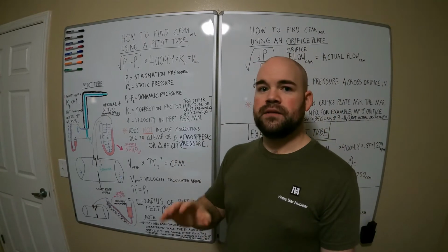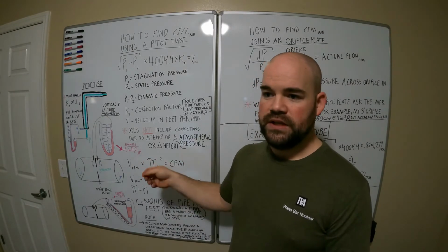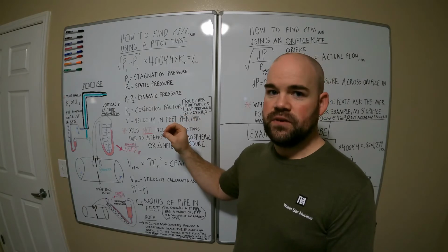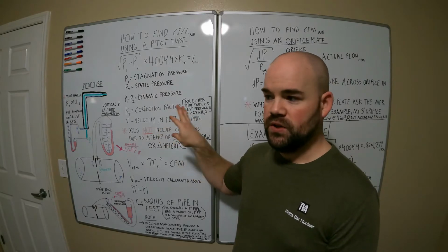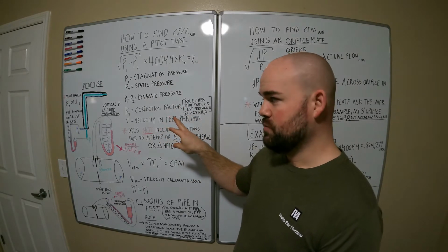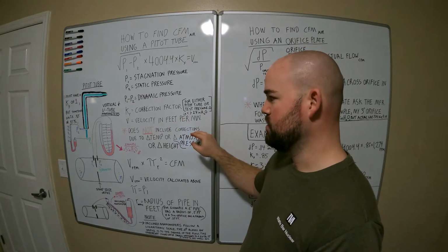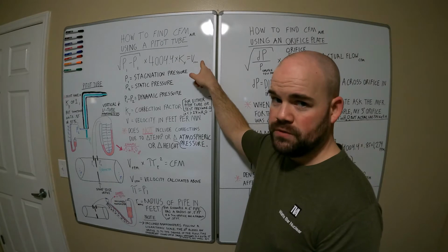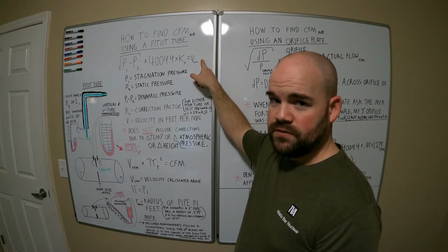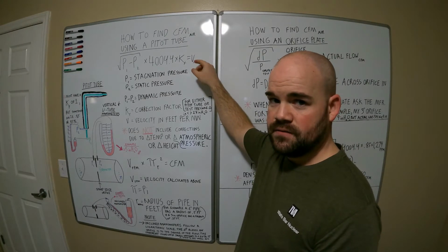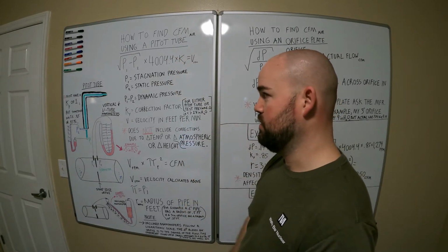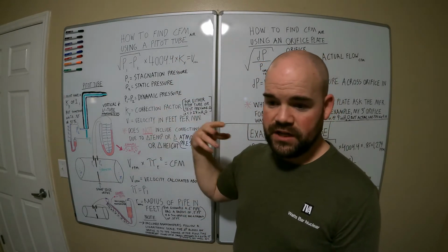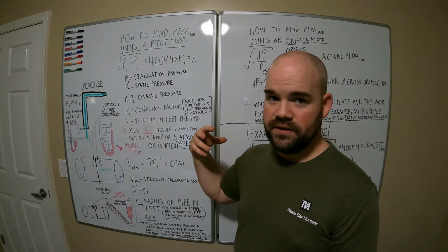That's important. There's an adaptation to this that you can do to take those into account, but most people that are going to use a static pressure manometer can do the correction factor, and it's just look up Bernoulli's principle on compressible gases, and it'll tell you how to do that. There's a lot of calculators online. There's electronics, which I use. I use a Testo 510i.